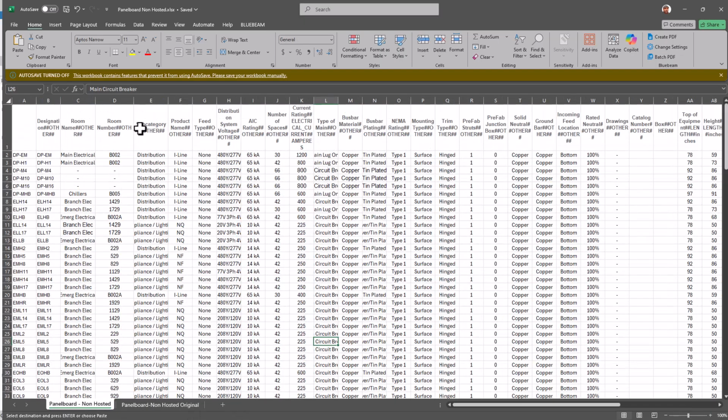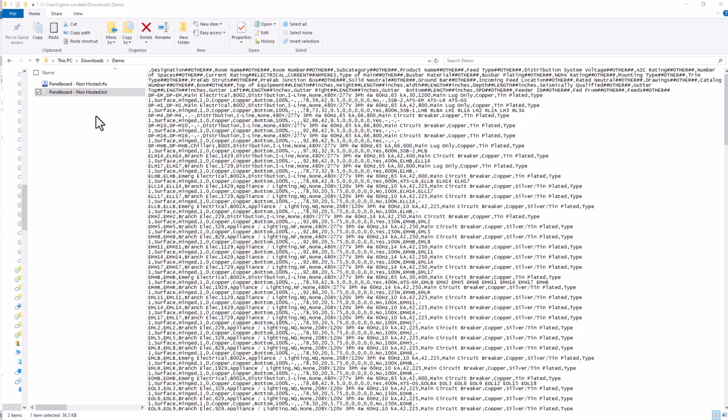And as you can see here, I come in here and I basically add all the information to make it a type catalog. For those of you who don't know what a type catalog is, it's basically a CSV file that you put special headers on so Revit knows how to read it. The extension you want to put on the end is txt, and you want to make sure the name of the file is the same as your Revit family. So once I create this type catalog, I can then take this information and bring it into Revit.